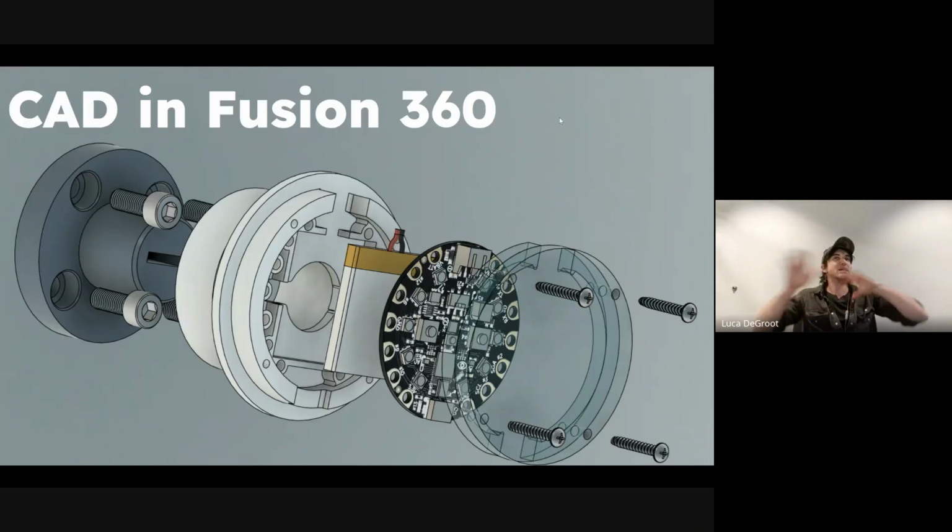So you can have mesh-based models of a Klein bottle, which is a non-manifold surface, a surface that can't exist in real life. The Klein bottle is an example of something that isn't a real model, but you can just have points in space, whereas a solid modeling program tends to have solids. They have some volume, they are enclosed. There's also something called surfaces, which would be basically zero thickness.